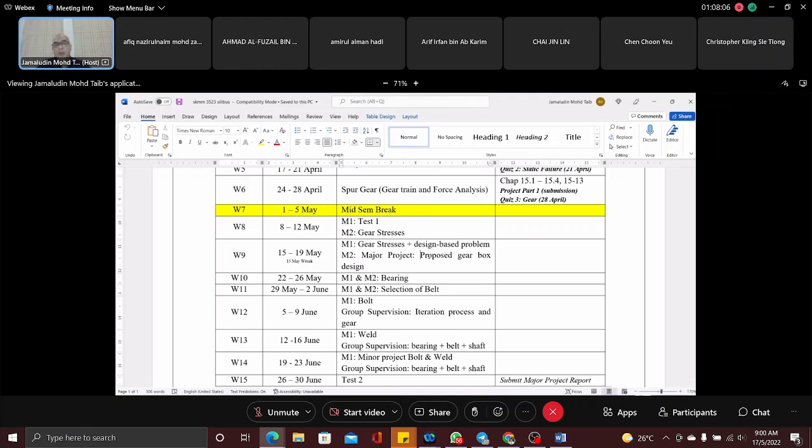6,000. That's good, because the maximum load as we work is 5,000. That means the machine is fine. The maximum RPM for the hoist will be 25. That's fine, because I asked you for a maximum of 30. That means 25 is good.